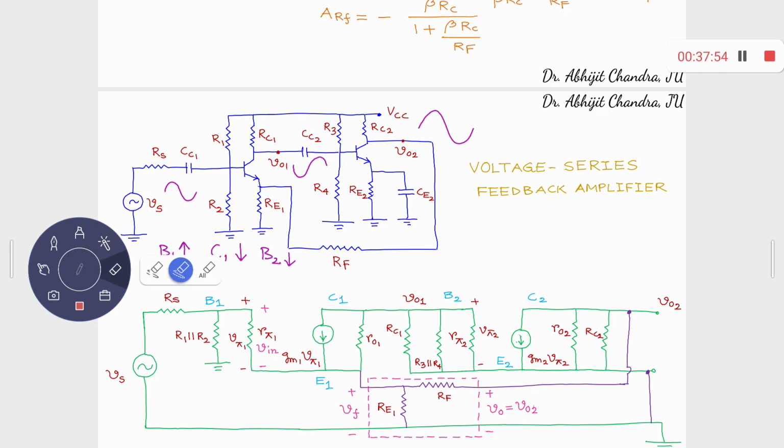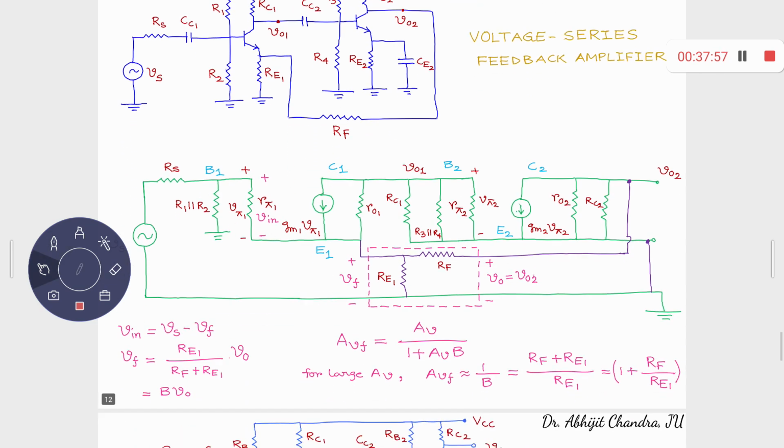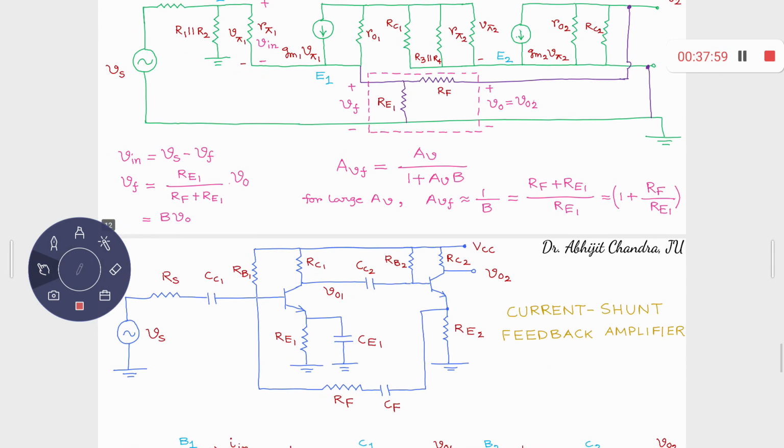So now let's directly move into the circuit. Only one change we have made. This time, I don't want any local feedback at the first stage, because that part is not our business this time. So we have used a bypass capacitor, so that no local voltage series feedback is present there. The extra capacitor, I'm coming to that.